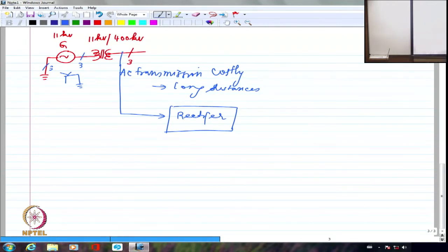So we use a lot of thyristors in series. Normally that's what we do. Whenever I'm talking about this rectifier, it is going to essentially use a large number of SCRs in series. Now the rectifier has rectified the voltage, so I'm going to have a plus and a minus.